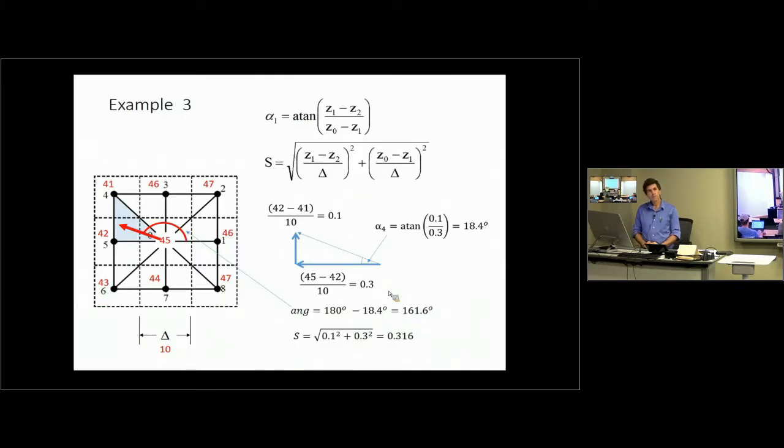So one of the things that I wanted to draw out of this was the red angle tells you what direction, so that's like azimuth. But the slope value there is telling you what's the slope going downhill, right? So you've got two different things going on here. You've got an angle that rotates around from the east over here, and then it gets to there and it goes, now I go down because I've got a slope on there. So there's two pieces of information. Now you could actually do an arctan on the 1.1 and 0.3 and get a declination slope as well.